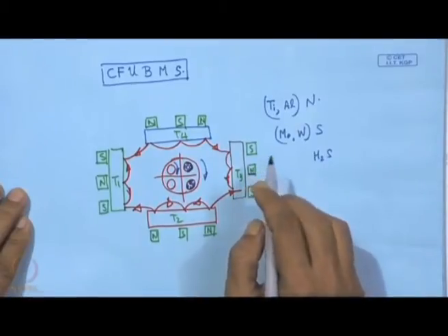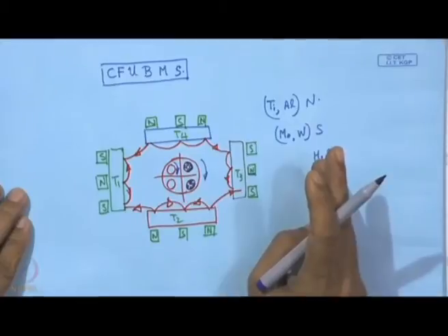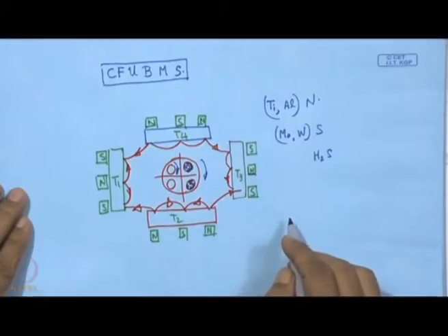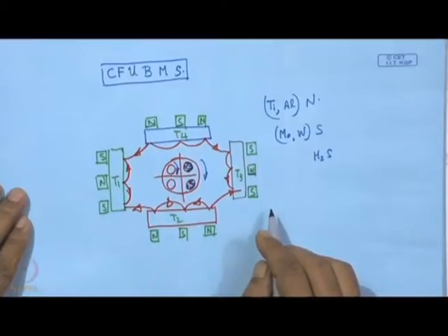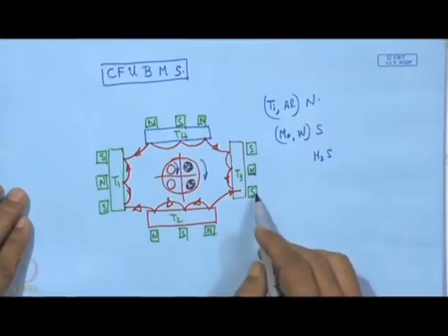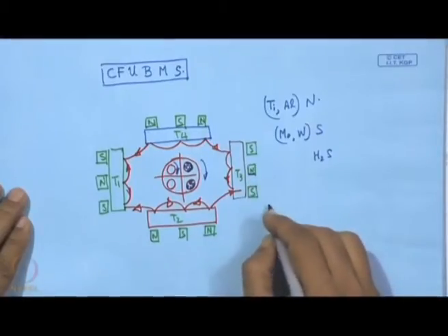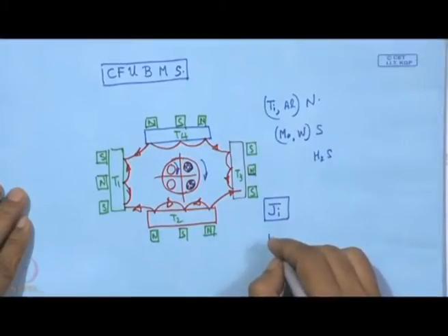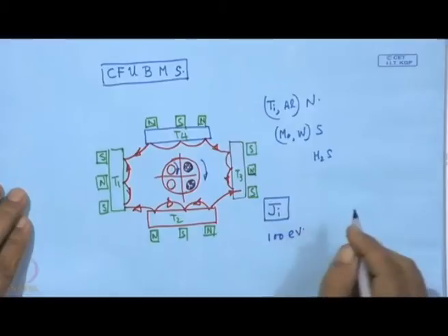on the substrate surface, which will be useful in having impingement or showering on the material which is condensed on the surface of the substrate, and at the same time with this ion flux density, J_i, its energy should be kept well within tens of electron volts.